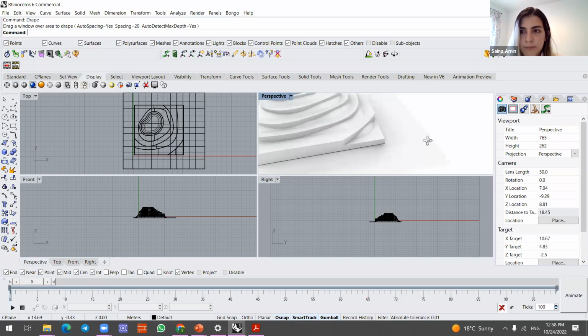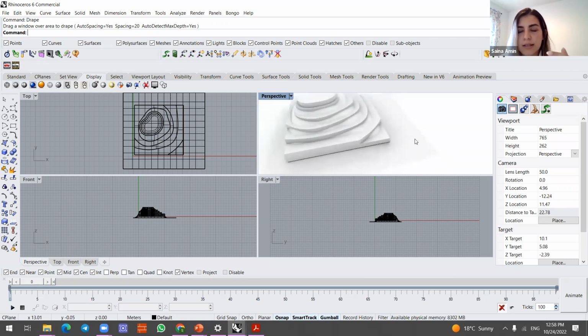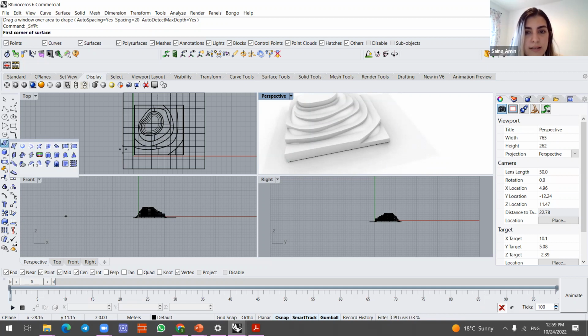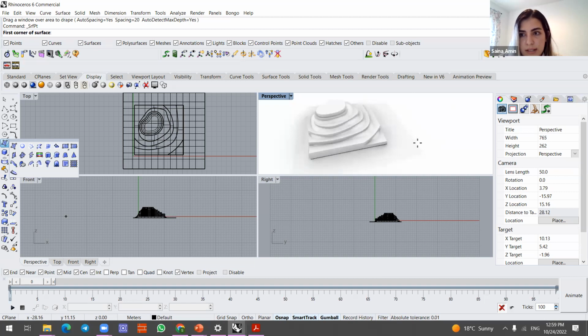After this one, when we do the split, it changed to solid because it's the intersection of two surfaces. And if there are any parts that remain or any hole or gap, we can go for the loft and connect the edges as I showed you here for creating the surfaces. So we would be good after this one if you did it.